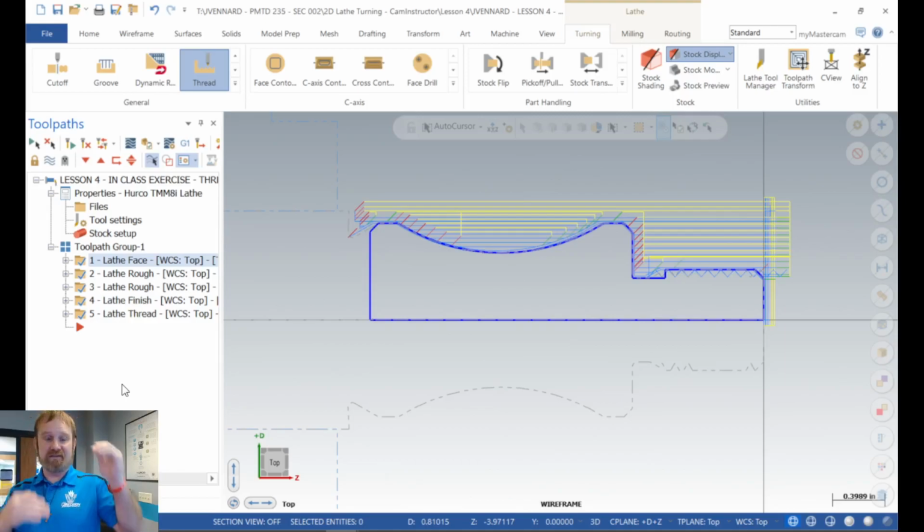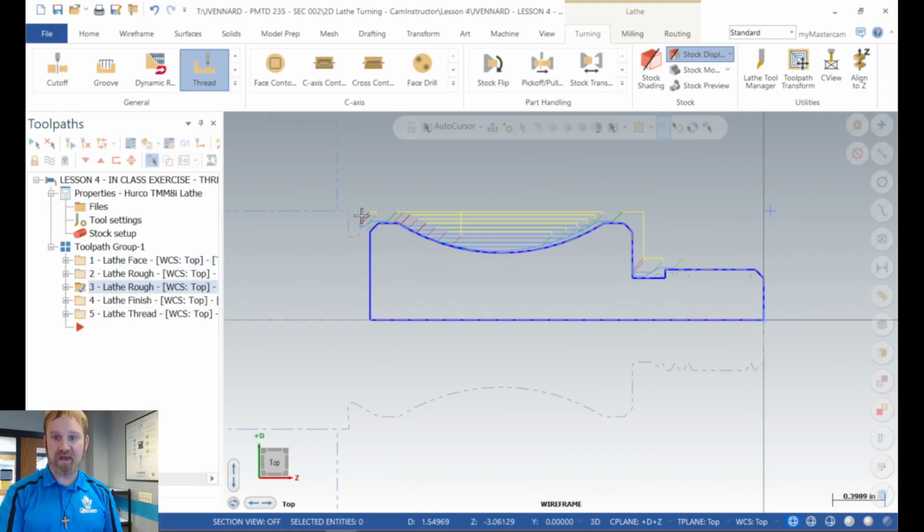It might be a glitch. For some reason, when I created those toolpaths, it didn't create the retract position. It didn't retract up and over. It basically is trying to go straight from the end of this toolpath right here and then come straight down and across there. Something in the batch processing in the background didn't happen. So what did I do? I just selected them all, regenerated them, let them all recalculate, and now it verifies correctly, and I feel much more confident about it.